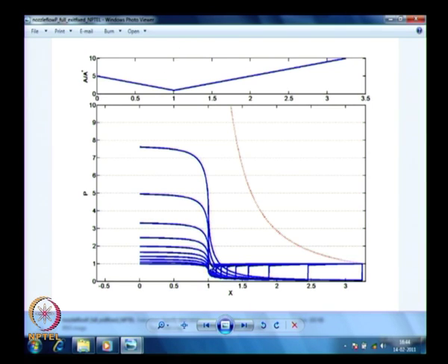Why will the pressure at the throat decrease for initial cases? Initially it is subsonic, where in the very first case there is no flow, so pressure is the same as atmospheric pressure. After that there is some flow, but it is all subsonic, so it will go below and then increase to atmospheric condition. That is the reason it is going to decrease initially. From there it will decrease, after that all the curves will go up. Only if you plot it better you will see it nicely.